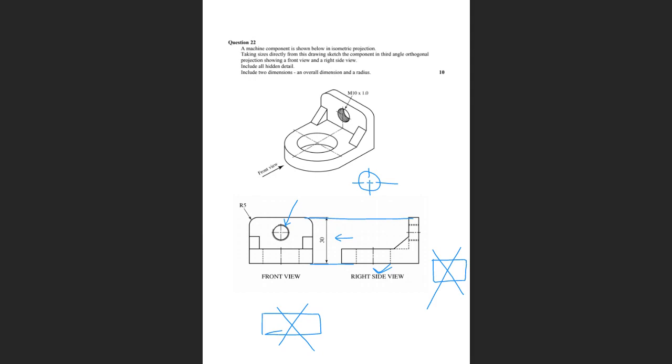And if you want to show a thread, you work out what the pitch is, and then you put a concentric hole around like this, and you generally leave a gap in the top left-hand quadrant. Some people leave it in other quadrants, but it's normally done in the left-hand quadrant, and that tells you what an internal thread looks like on a drawing. And you can see that it's shown here, the hidden detail showing the thread going through there.